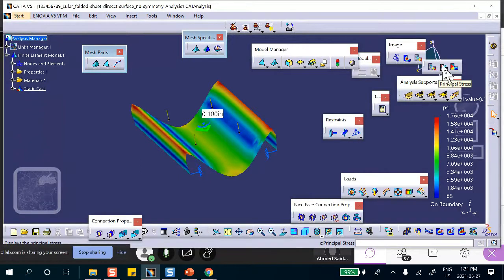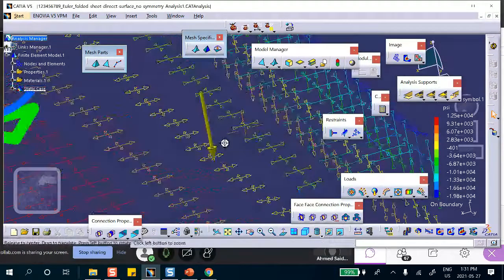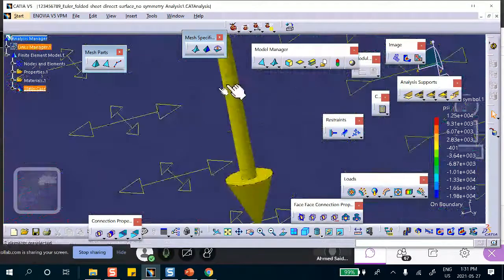Look, I'm going to click on it. Principal stress, right there. Okay, let's zoom in. Isn't that the kind of thing that you did? Because these are now two-dimensional problems. The stress through the thickness is 0. That's the assumption with shells. So this is the biggest principal stress in plane, which is 2,200. And this one is 360.